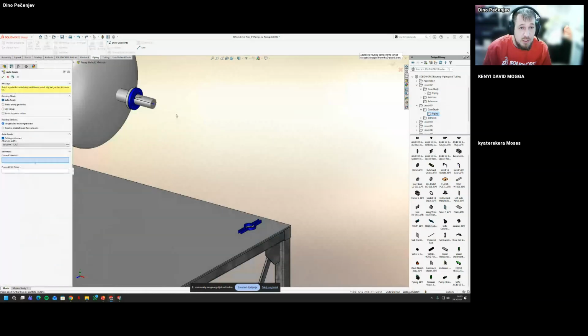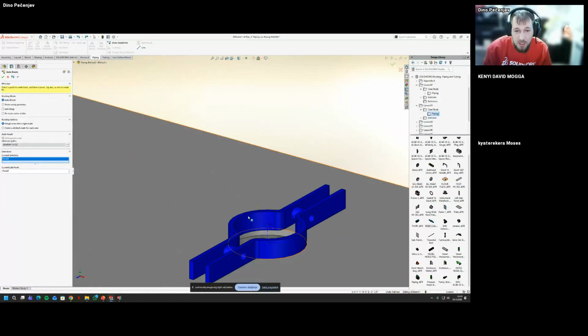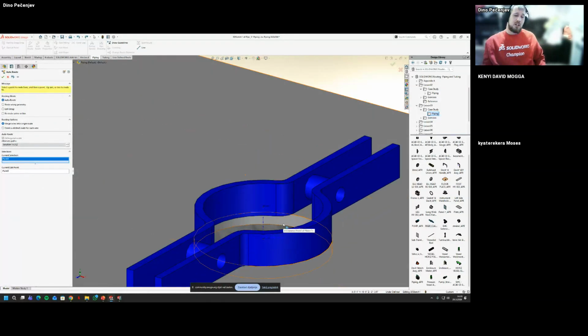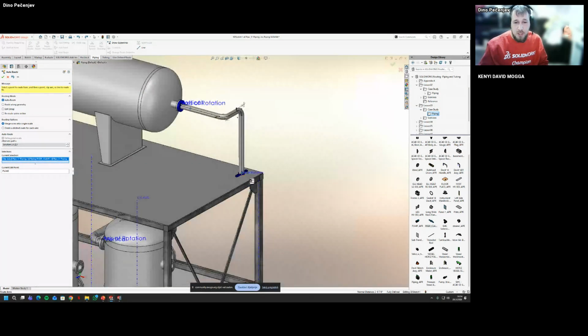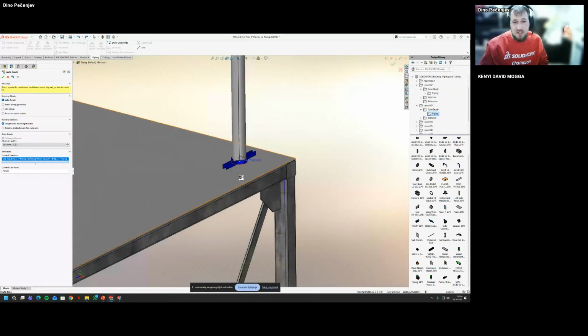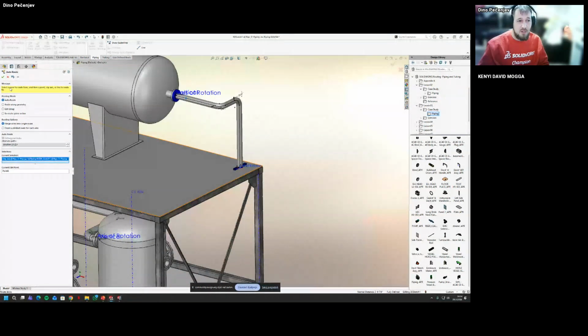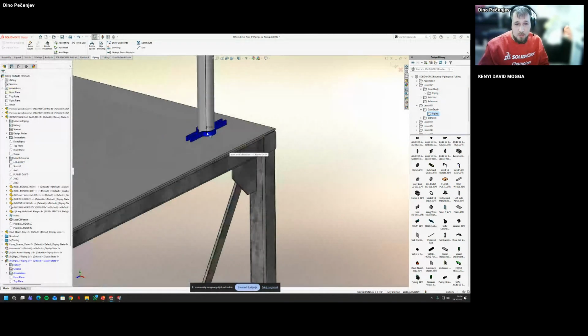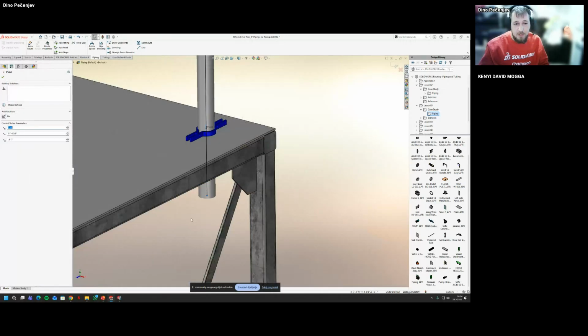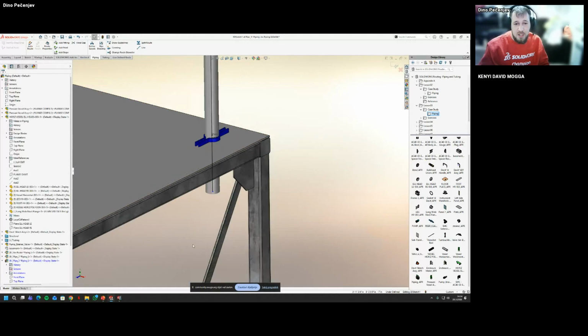And for this part, I can use the auto route. And the important thing is the clips don't need to specifically be geometry. You can actually use also virtual clips for the ease of the routing. So I'm just going to use this part. I'm just going to use the axis, and this part of the route is done. And I click done. This part is completed. So if I run down, this is all right, and it's set.